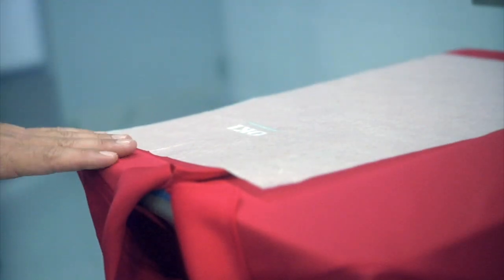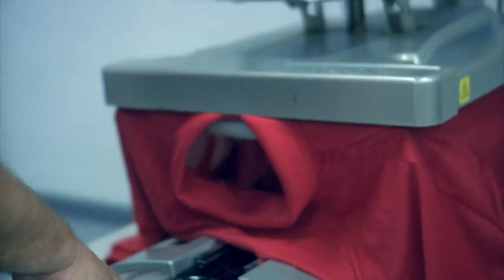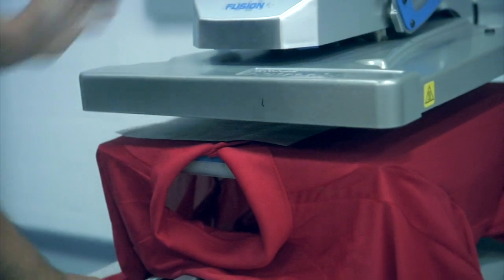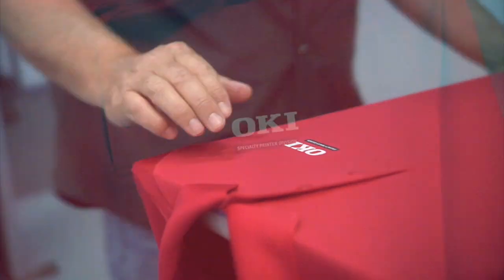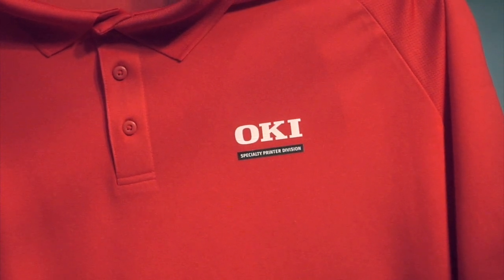The final step in the pressing process is to remove the sheen and set the transfer. To do this, place the shirt back onto the press and lay a silicone sheet or parchment paper over the transfer. Press the shirt again for 10 to 20 seconds at the same temperature and pressure that you used for the previous step. Your digital transfer shirt is now complete and ready to wear, display, or deliver to your customer.